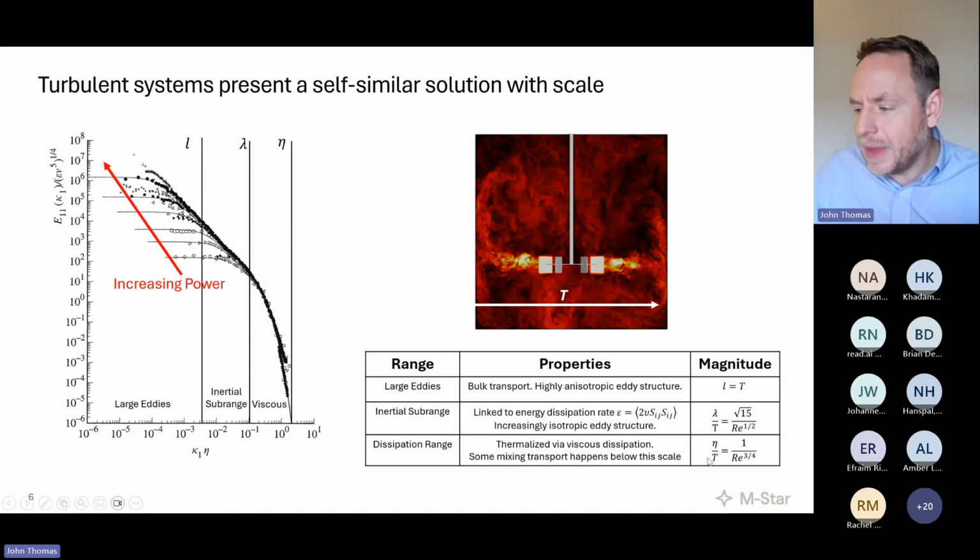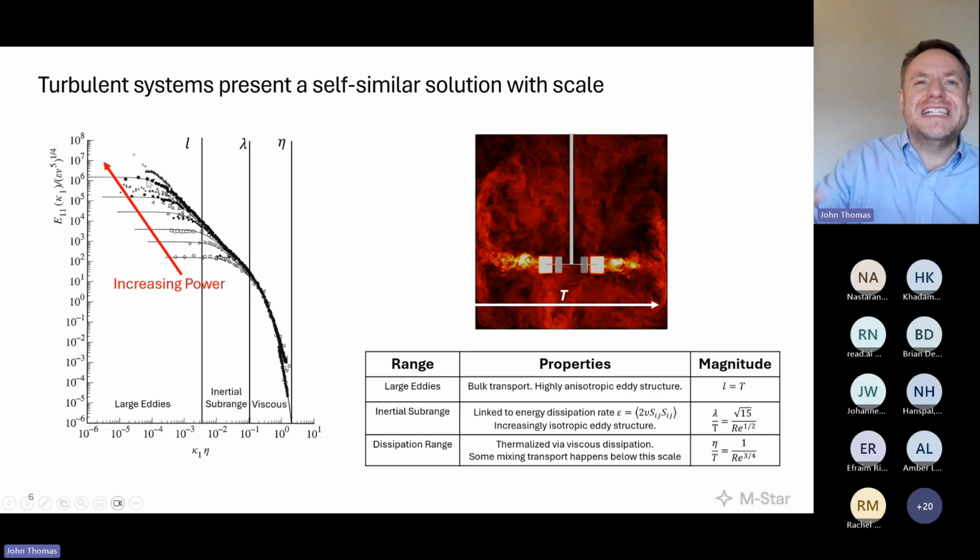So importantly, as we go to larger vessels, our integral scale eddies will change, but those are the ones we're already seeing so well. And even though our grid resolution necessarily gets bigger, its proportion to the overall scale is linked to Reynolds number, which means that even though our grid's getting bigger, our subgrid length scales are increasing in the same manner, which means the resolution is self-similar.